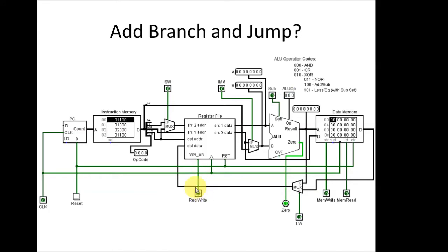So the way that we're going to do a branch and a jump is to make sure that we can take two values from source, which we've already got with the SW instruction, and when this is 0, we want to be able to write. So we'll have a connection here from immediate to the input on the program counter, and we'll be controlling this LD signal here.